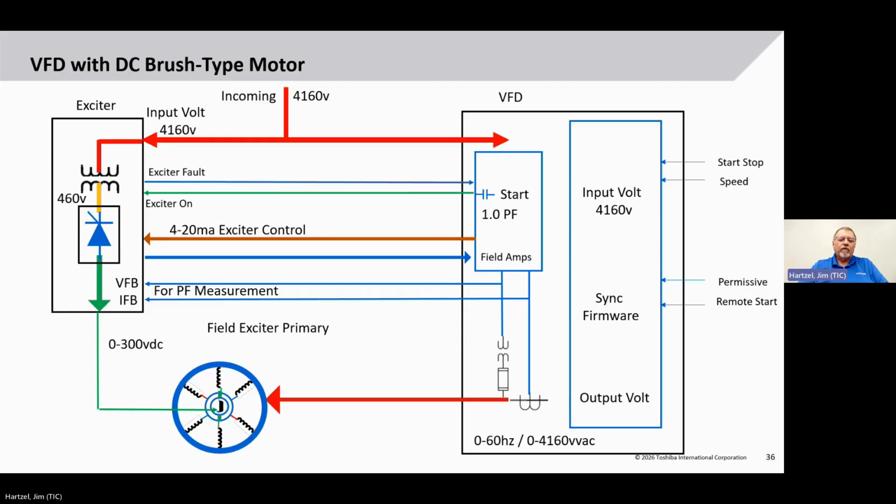So when we start off, we're going to already be synchronized with the magnetic field. Remember, previously we looked at you start it and bring it up to speed and then synchronize. Here on a drive, we're going to synchronize it. Then we're going to apply the voltage to the stator. So that's going to be different. It's going to start synchronized and it's going to stay synchronized throughout its speed range. We have to control and run at no more than unity power factor.